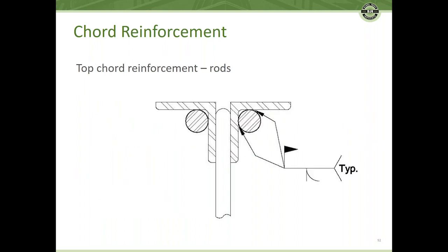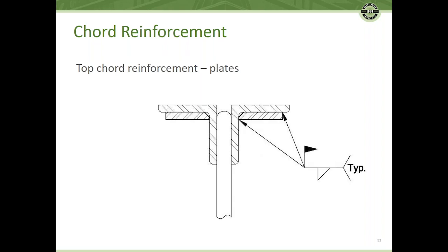You can see placing rods in the heels of the angles and welding them. That's a good, easy way to add material. You can see that when the webs are placed in between the chords, you've got plenty of real estate there to add material. Here's another example of adding material, some plates. Note that due to the fillet of the angle there in the heel, that plate has been beveled so that it'll fit up tight against both the horizontal and vertical legs.